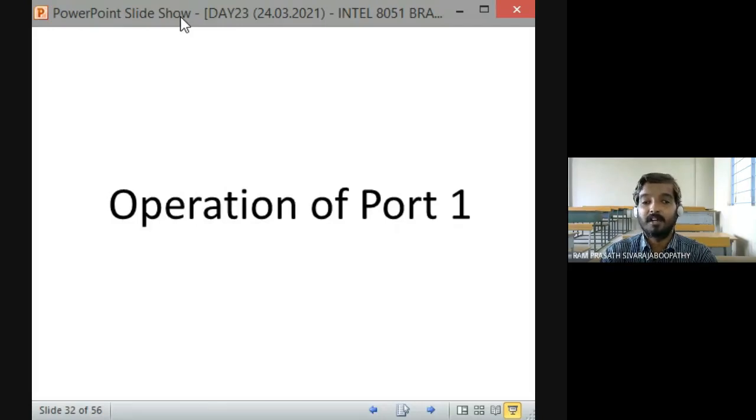Logic 0 means what? Set or reset. Yes, very good, Shivakumar. CLR, very good. CLR space the port pin name. That's all. So clear. Fine. If I want to write logic 1 on the same port pin, what do I have to do? Kindly interact. See, in this particular topic, we cannot learn without interaction.